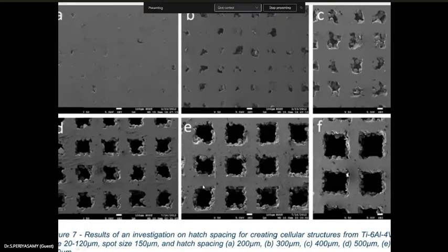The grain structure will be reformed and recrystallization will happen. So in those cases it will have a gapless or poreless grain structure. That is normal in casting and forging. Here, because of this natural feeding and gravity-based changes, there is a possibility of porosity.